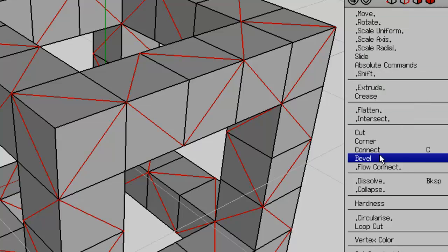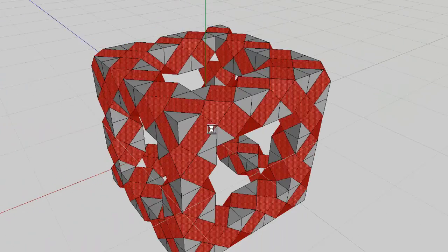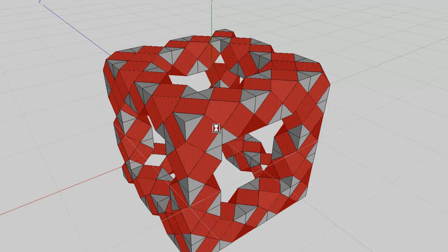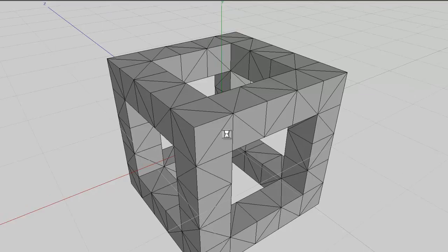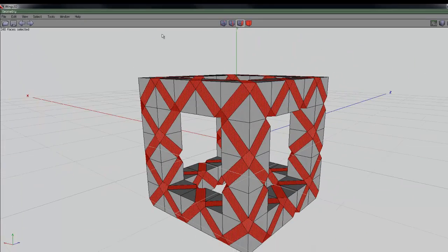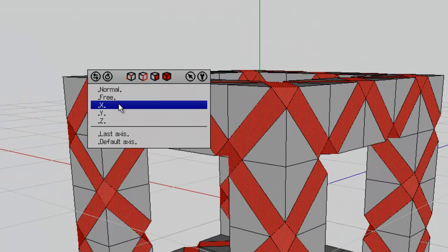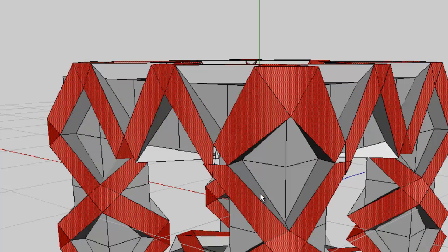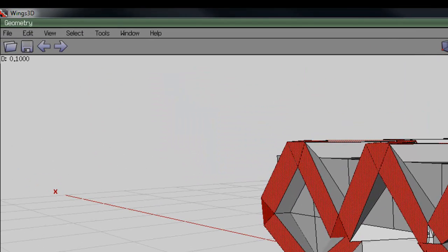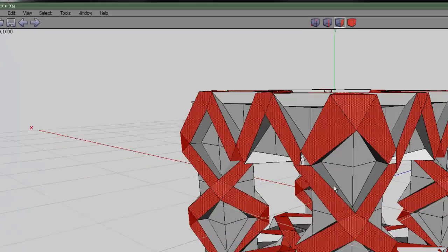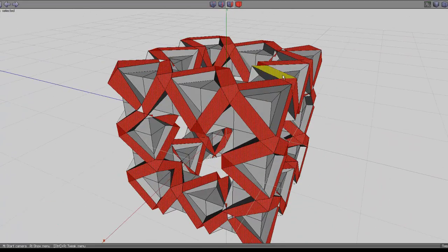So I can now bevel the shape, which allows me to do that to the shape, which is a bit interesting. Now if I again press Control down, I can do it in discrete steps, and I'll just use one step, so that's 0.1 there up on the left hand side, it shows it there. And then I'll right click and I'll extrude the shape, use normal, and holding the Control key down, extrude it a bit, so that's now, I can go 2 or 0.1, I'll go 0.1.